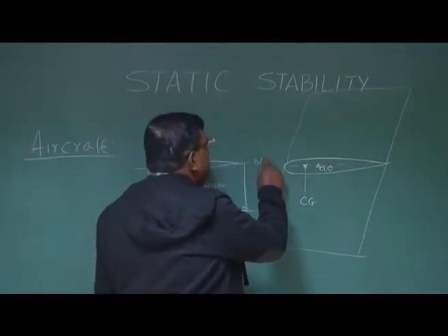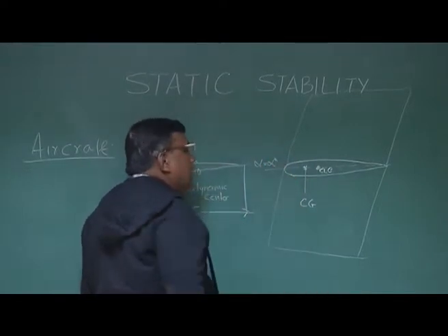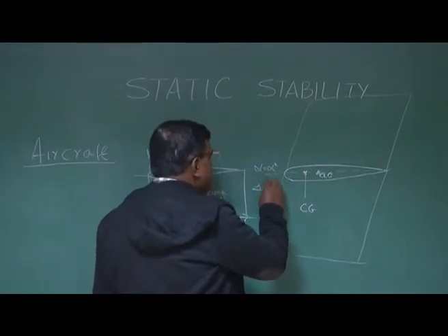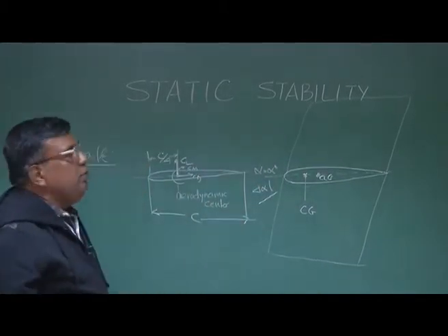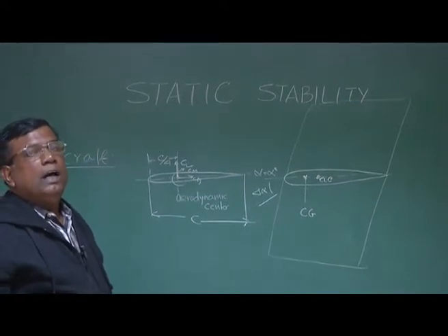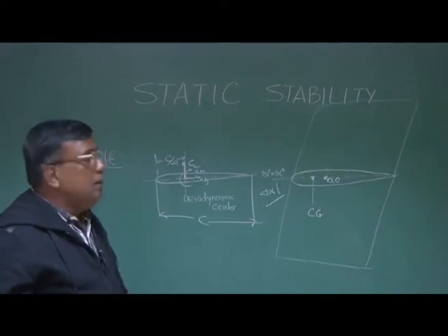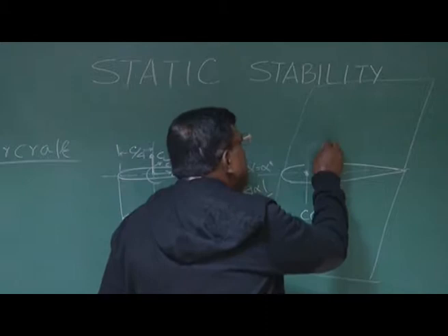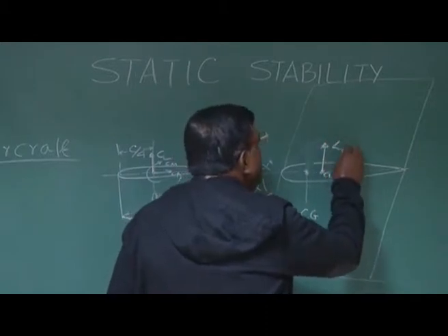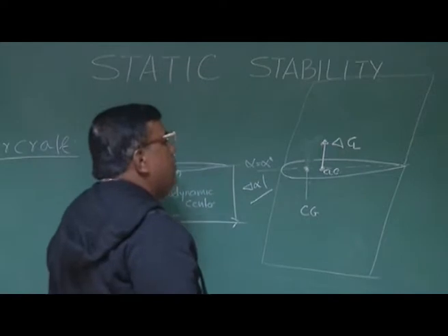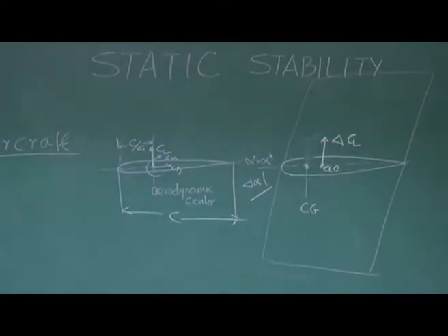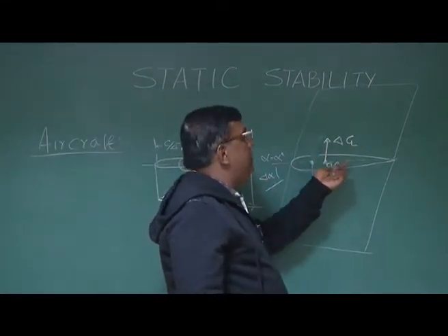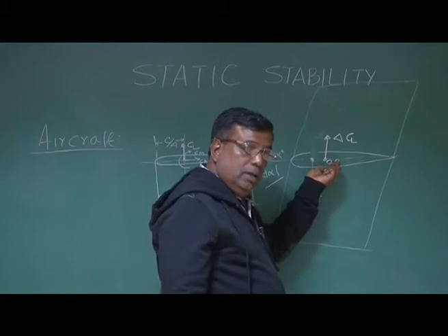Let's say this wing is flying at alpha equal to alpha star, and that is the equilibrium. Because of some disturbance, delta alpha, the wing is going to respond. We are looking for its initial tendency. If there is a delta alpha disturbance, then a delta CL, the lift coefficient or a lift if I multiply it with dynamic pressure, will be generated, and that can be represented effectively at the aerodynamic center. We have agreed on this point.